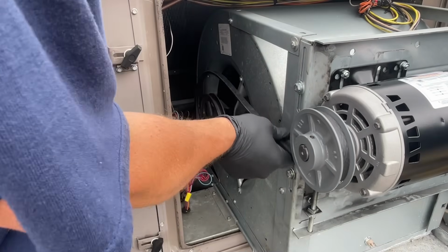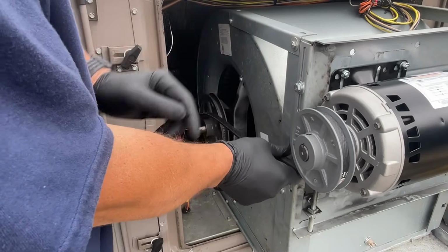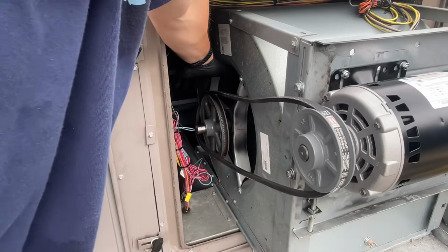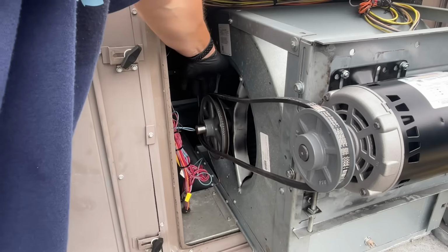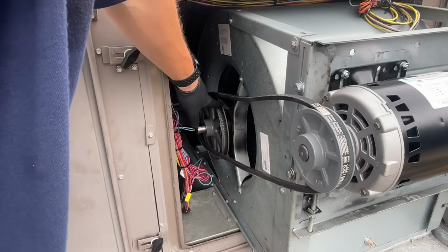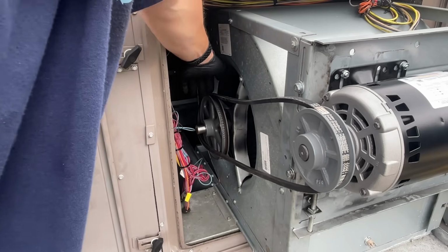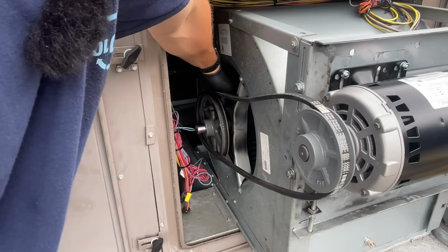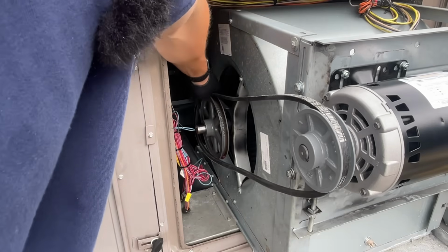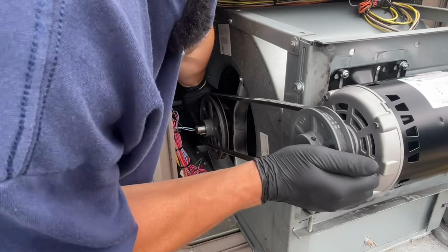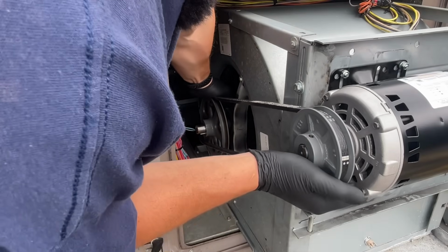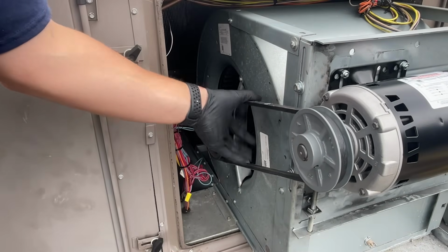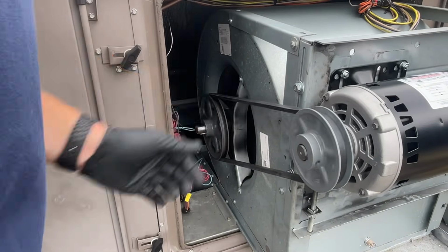So in my prior videos, I always told you guys, you go from the smaller pulley, generally speaking the motor pulley, to the blower pulley. You put it over top. Remember, hands are free and clear of this, which is where our belt would ride. So I like to grab the spokes here of the pulley to get some leverage with my hand flush over the top. And then I'll use my backhand here as more leverage. So we'll turn it and boom. That belt tension looks perfect.